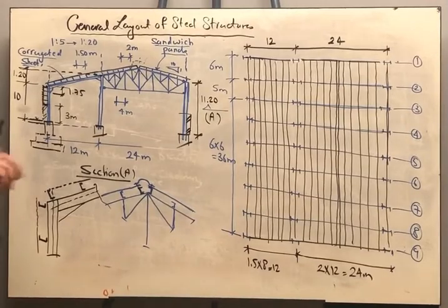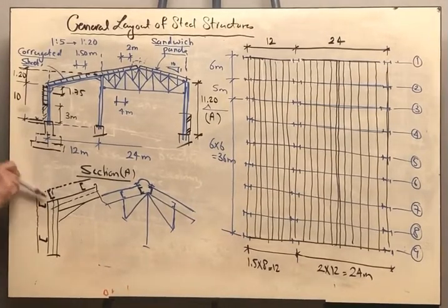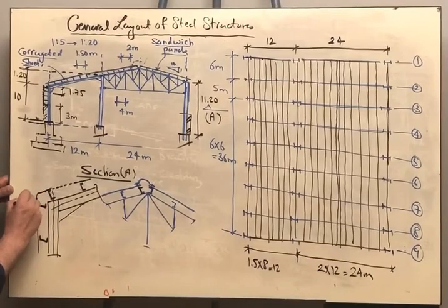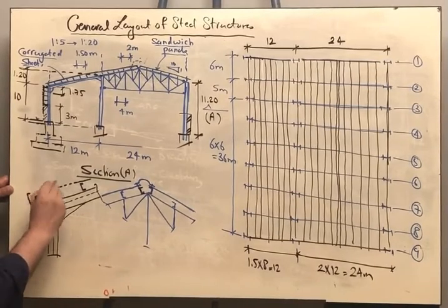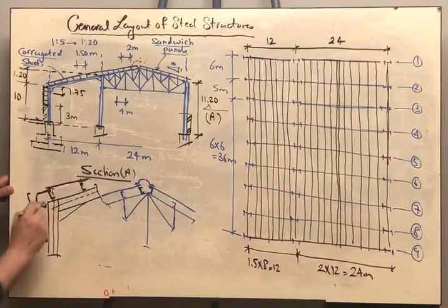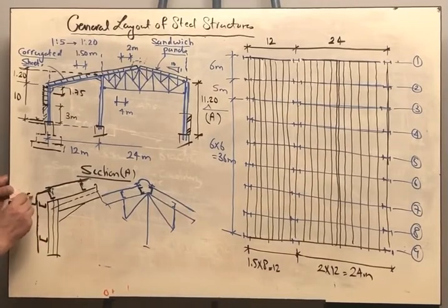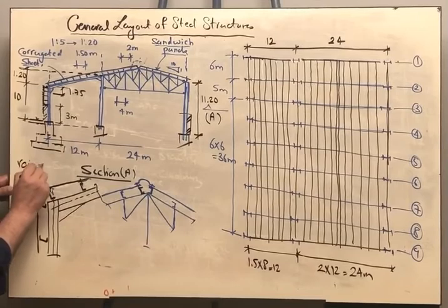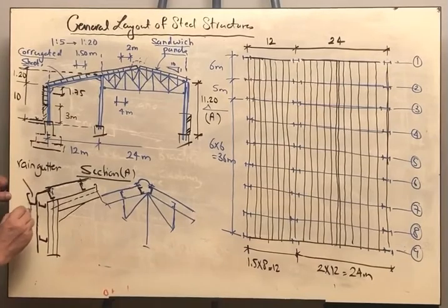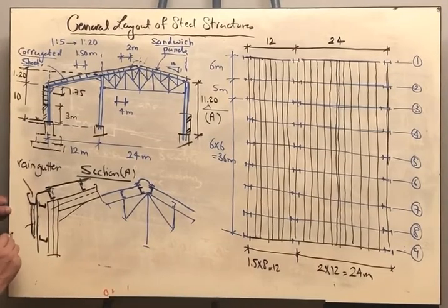Again, the corrugated sheet cannot be bent. The water will transfer in between these two elements. I need to close this part. How do we close it? We close it using rain gutter like this. This is called rain gutter. So the water will collect from here and will collect inside the rain gutter, and there will be a pipe that will collect the water every 6 or 12 meters. This is called downspout.